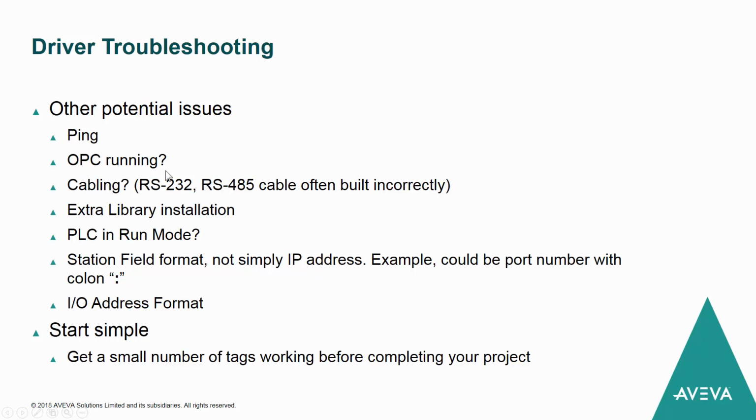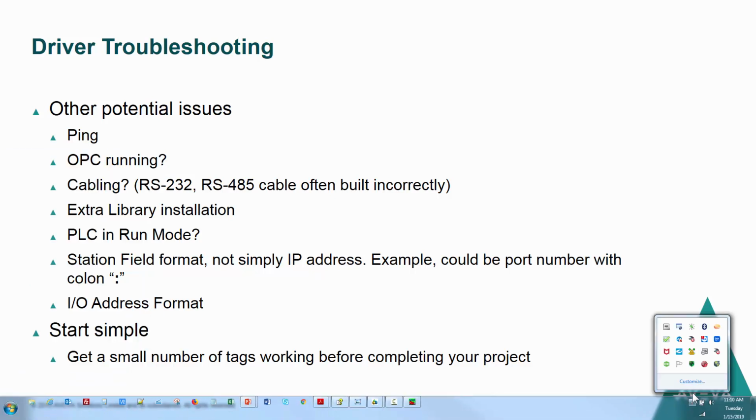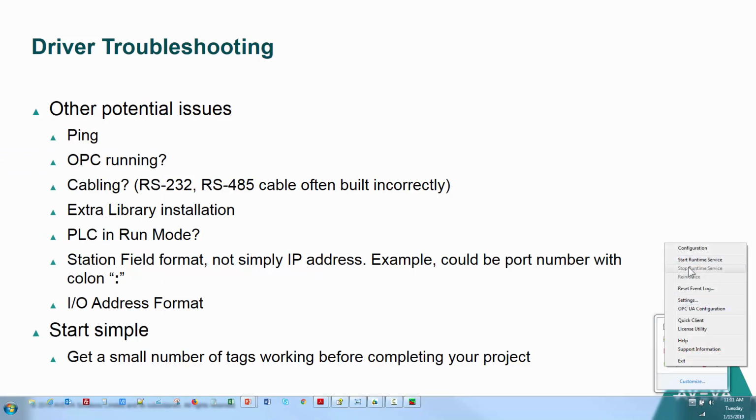Is OPC running? One of the things that happens a lot to me, because I often do OPC setup, is I've got Kepware running here in the background, and if I right click, I have stopped it just before I started this video. If my OPC server, and it doesn't have to be Kepware, it could be any OPC server running in the background, is running, then in this case, for Modbus specifically, I was communicating Modbus to this server and it wouldn't communicate to my simulator, so I had to stop this.